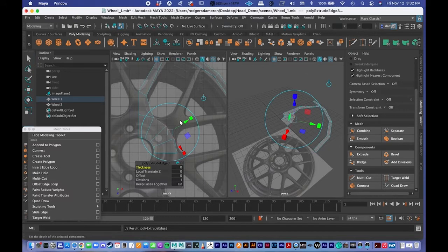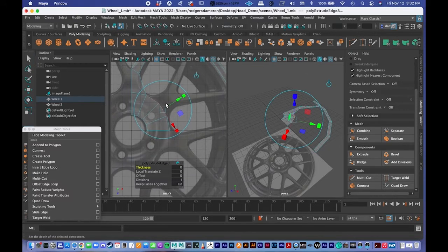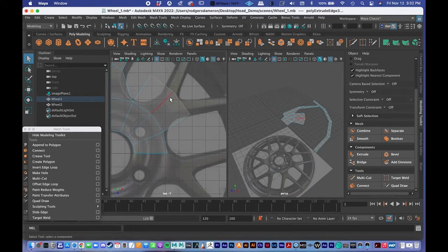So I'll extrude, and again I had this edge and that edge selected right there, and I'll just drag it out and press Q. Not even worrying about getting it exactly right, because I'll do that in this step where I right click and go to Vertex. I'll move this vertex to that center point. I'll move this one in here, this one in here.